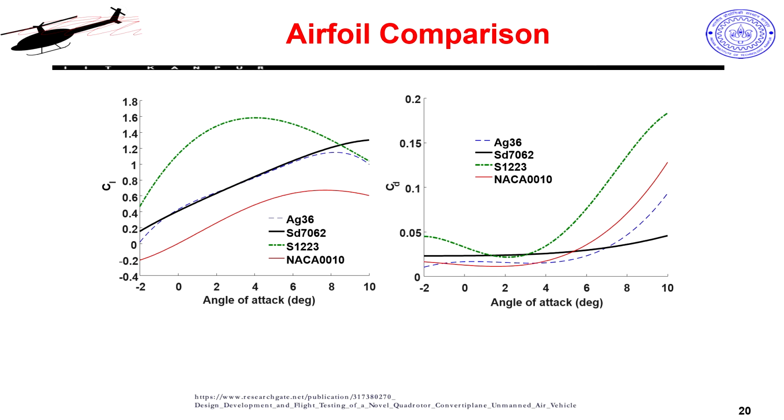So, with that I am showing you a comparison of 4 different airfoils. This one is your NACA series, NACA 0010. What does this mean? The first 2 digits tell you the camber, how much camber it has, so it actually tells you the percent camber and the location of the max camber, because that will determine the shape of the airfoil. And the last 2 digits give you the thickness. So, 10 means it is 10% thick.